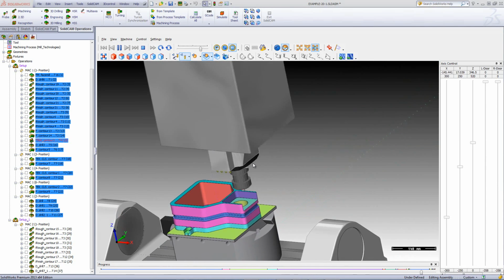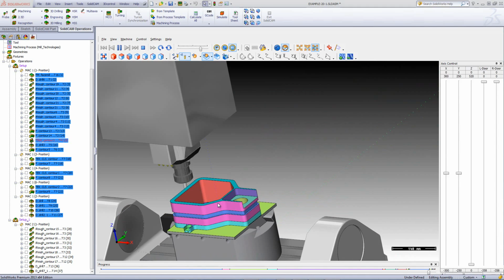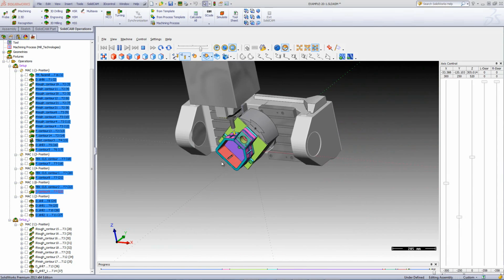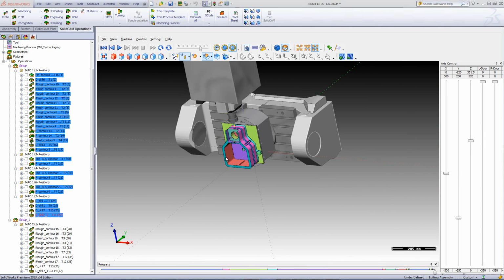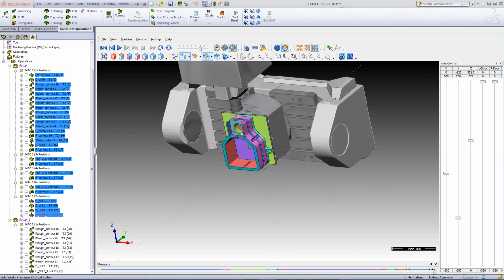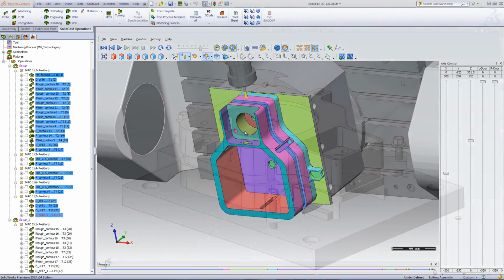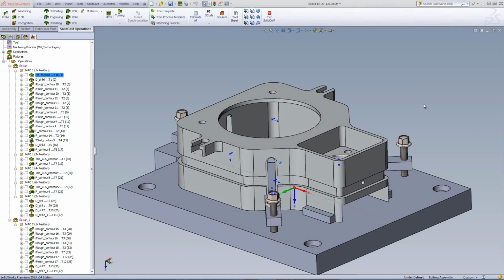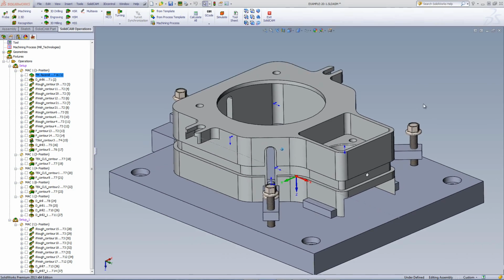And now the machine is actually going to turn to start working on the slots as shown over here. Working on each slot with the indexial machining for those areas as well as the holes over here. Now that I've completed the first side of the part, I have to do the second side, and for that I have Mach 2 because I have to do this with a different holding fixture as shown over here.